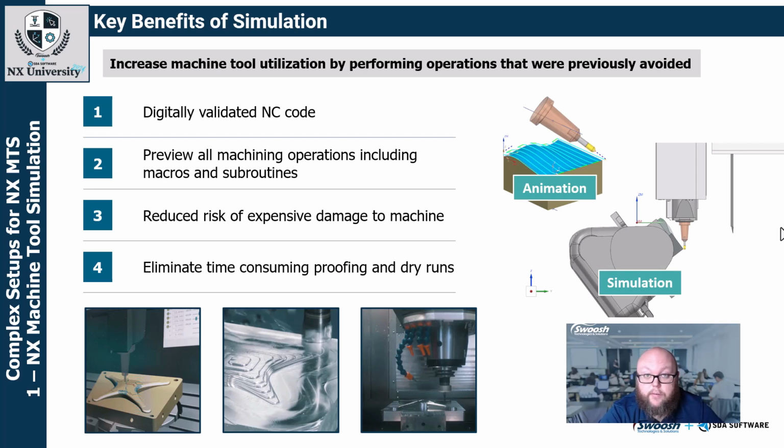So this is all in the digital world before it hits the shop floor. The last thing we want to do is get the programs out there, have the operators set everything up, and go to start the program, and all of a sudden they start running into problems. Over travels in the machine, syntax error in the code, crashes of the machine.